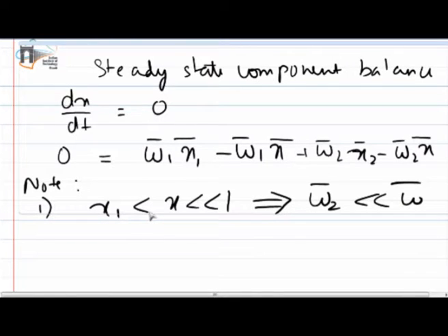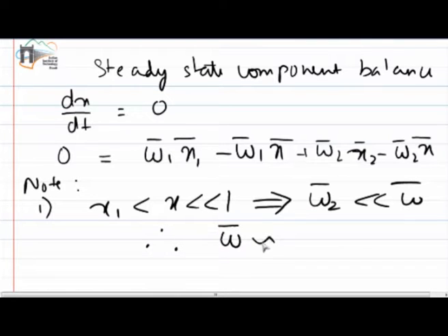Okay. So with this assumption, now think on this equation, that if the w2 component is very much less than w, where w is the final product or the weight of the final product, and w2 is the weight of the stream 2. So this means that whatever the w I am having is almost coming from w1, and w1 is constant for us. This is our second assumption.